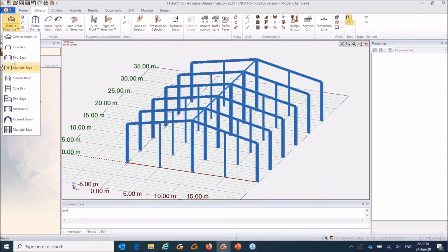From here you can see there is a library of different types of structures, and then you can customize the spacing, number of bays, the cross section of the rafters, of the purlins, of the side rails, of the gable posts, columns, anything. You can also create platforms, create openings, and add levels. It's actually quite useful. There will be a webinar around this specific tool next week, so I won't spend more time on this now.